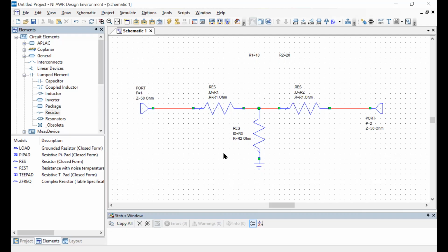And you can then say simple things you already know about voltage dividers, that the smaller the R2 is in relation to R1, the smaller the voltage here will be. That means the larger the attenuation would be as well. And that gives you a sense of how to think about how this is going to operate.